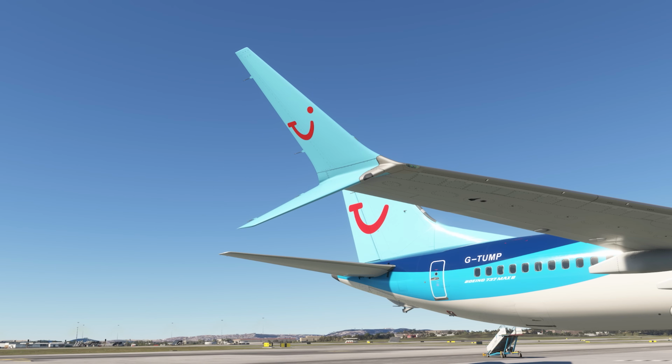So moving on to the winglets here, these are the advanced technology winglets. They're fitted to the 737 and it helps increase the aircraft's lift, thus reducing the fuel burn as well. They're absolutely huge. There's a bit of a fret with the fueling truck to ensure that they keep well clear of them, but they provide a fuel burn improvement of almost 2%. So these are the advanced technology winglets, and you see a lot of the NGs now getting modified to have these retrofitted winglets as well.